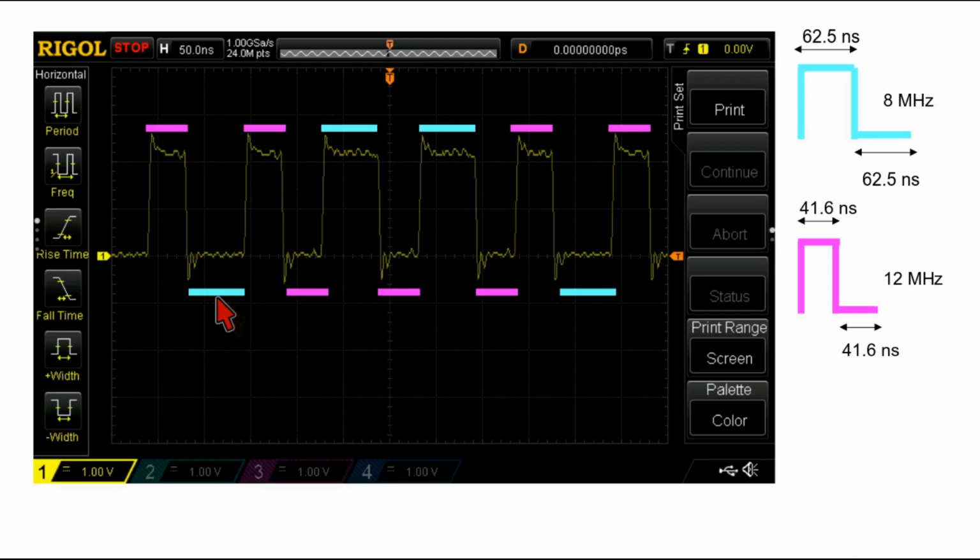There are dividers that can do that, for example the delta sigma fractional n synthesizer, but these are of course a lot more complex than dual modulus. Moreover, since all these dividers do is essentially a more thorough mixing of the n and n+1 frequencies while maintaining their average ratio, the basic observation on jitter based on the dual modulus principle is still valid.